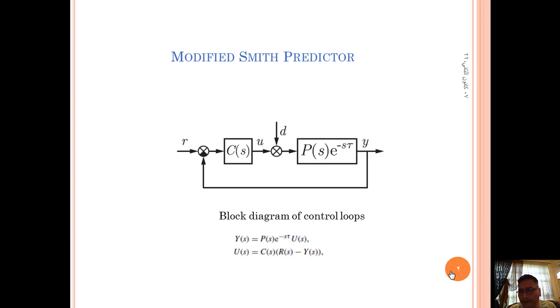In the case of a perfectly matching internal model, the modified Smith predictor technique is able to stabilize an unstable system. While this is not possible for the Smith predictor, the Smith predictor has disturbance response and the effect of initial conditions. This makes the modified Smith predictor possible for doing this with a perfectly matching internal model.